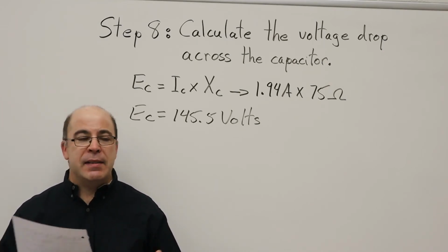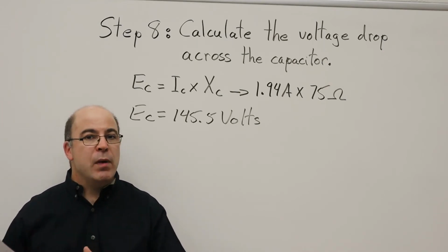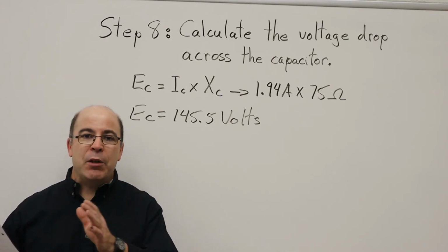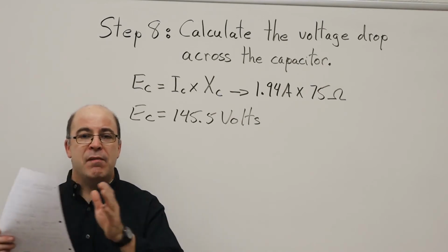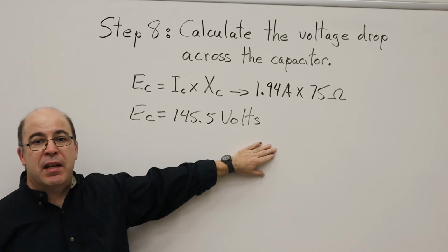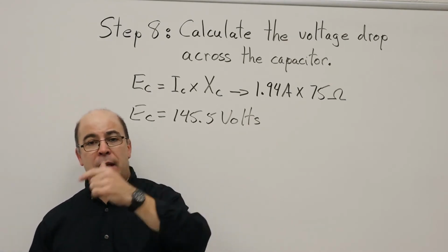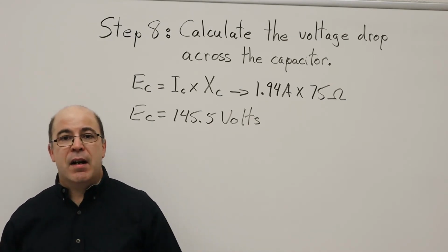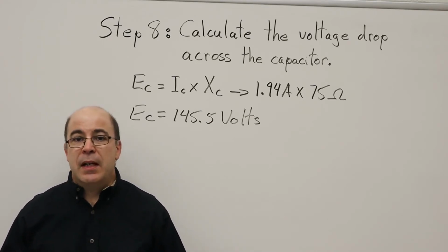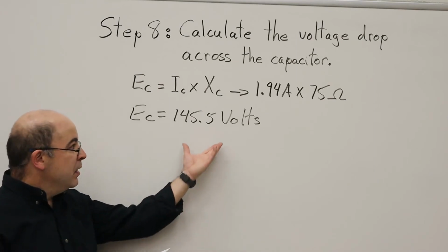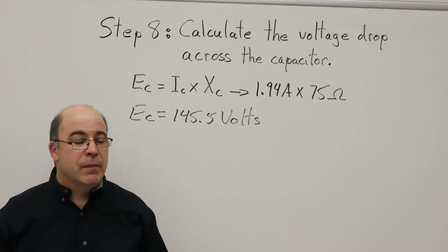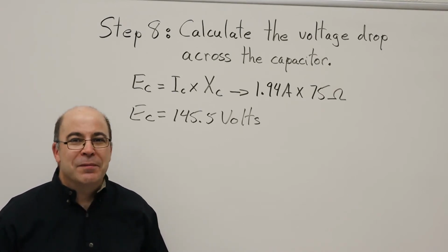And what we're having is a game of ping pong, if you will. I think it's the best analogy I can come up with, where you've got energy seesawing backwards and forwards from the electrostatic charge that resides inside of a capacitor to the electromagnetic field of the inductor. And at different points in the sine wave, this is what we're seeing. This is one of the reasons why we're producing really high voltage drops in a series circuit. And I will be able to prove it.